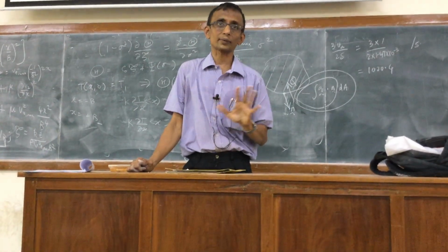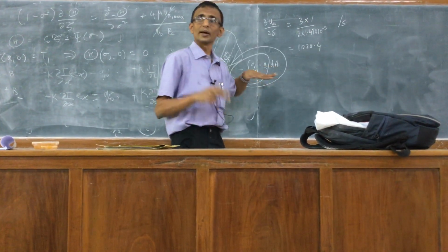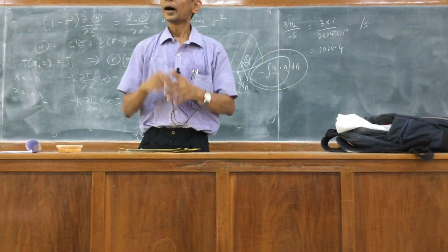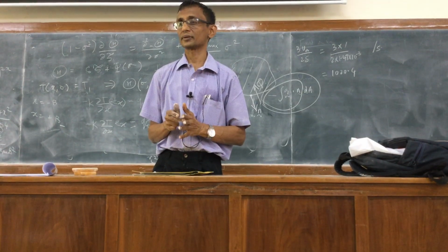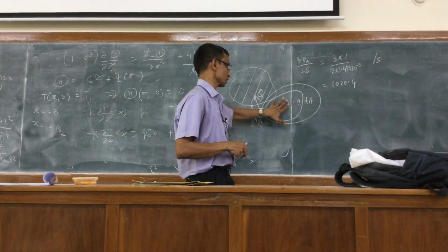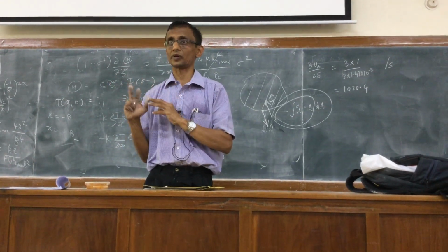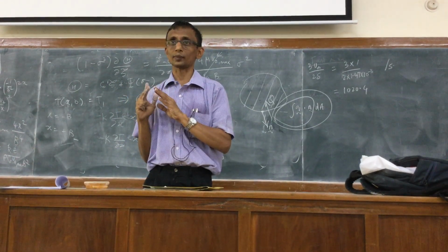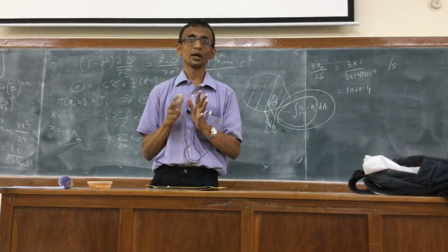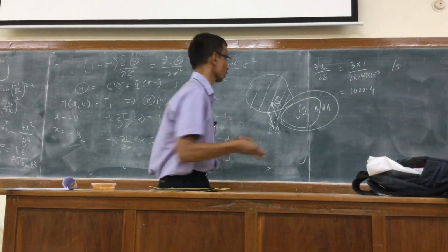That is the crucial part. There is a confusion because of the heat flux vector and the heat flux. Actually, heat flux is a scalar, and then you have all the sign conventions. Some books might simply define this as some h, and then this minus would not be there. Then that heat flux vector has a slightly different meaning from what we normally associate. So I am using the conventional way of treating the conduction problem. This is what you have to remember.